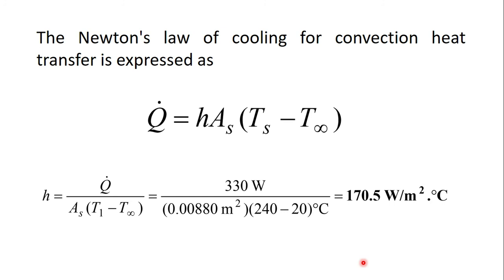The next step is to determine the convective heat transfer coefficient, and for that we will use Newton's law of cooling for convection heat transfer. The rate of heat transfer is equal to the convective heat transfer coefficient, times the surface area, times the temperature difference between the surface and T infinity, which is the temperature far away from the surface.